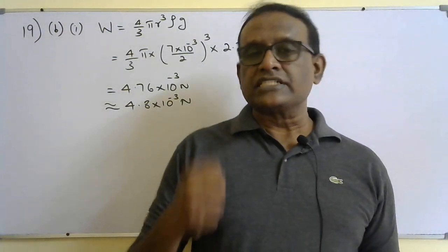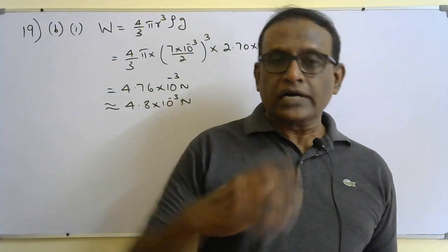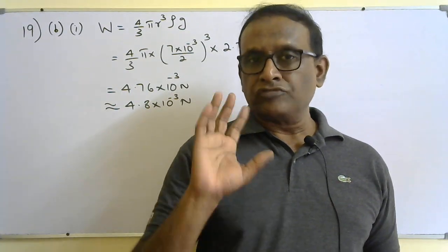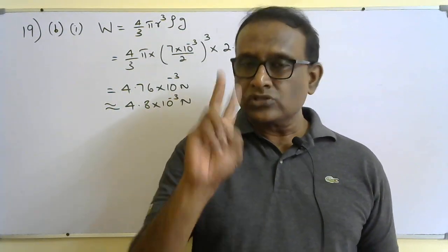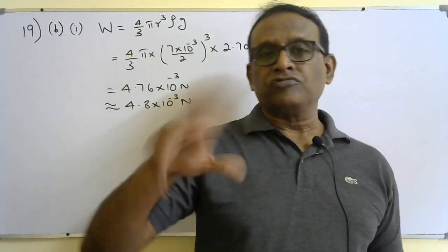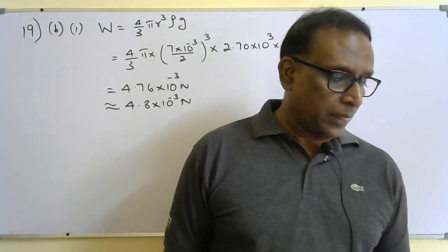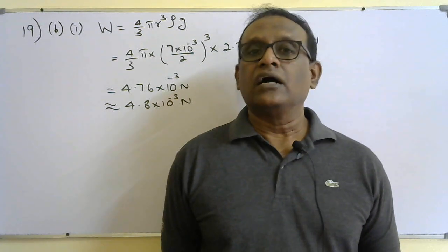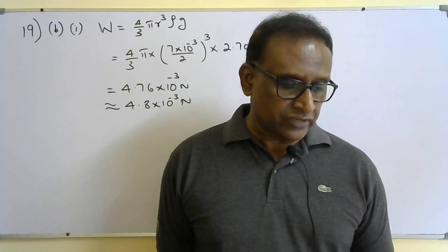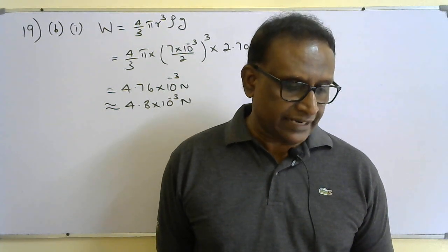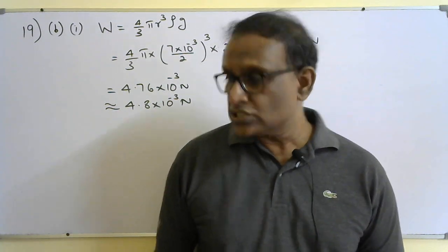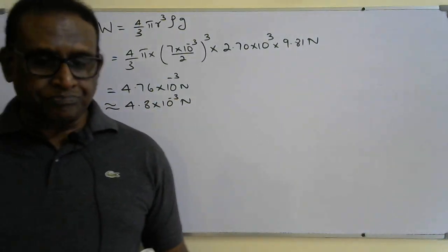Two conditions. First condition, the fluid flow around it should be laminar. Second one, we can use Stokes' law only for spherical shape objects. So two conditions. It should be a sphere. Second one, the flow of fluid around the sphere must be laminar. Otherwise, we can't use Stokes' law. Density of the glycerol is given. Viscosity of the glycerol is also given. So we need to decide whether Stokes' law is applicable.